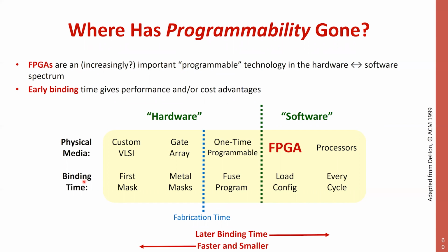Otherwise you look on Wikipedia, but field programmable gate arrays, these circuits that are built but don't have yet a logic function, a hardware function until you load a functionality, they make a perfect host for what you do with high-level synthesis, right? You take your C program, now you convert it into a circuit. If it were possible to have immediately a fantastically efficient circuit, it would be great, because now you put it on the FPGA and you use the FPGA to compute, potentially in a much more efficient way than your processor will do.